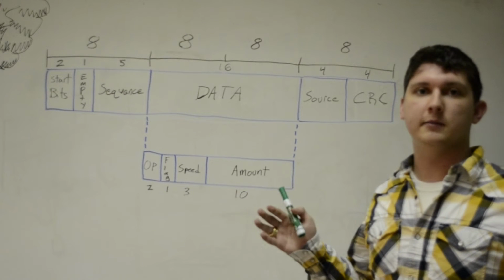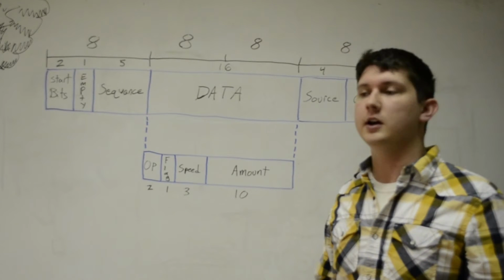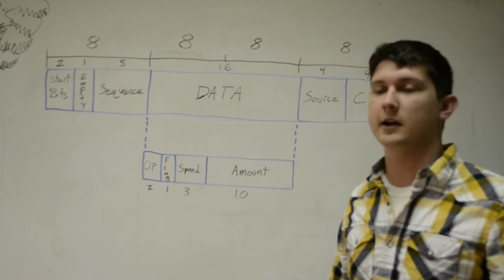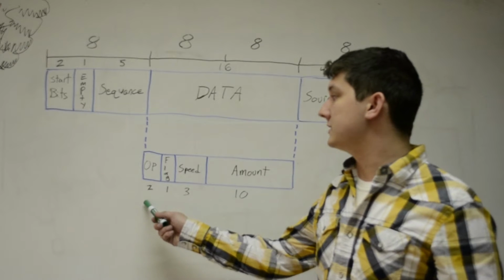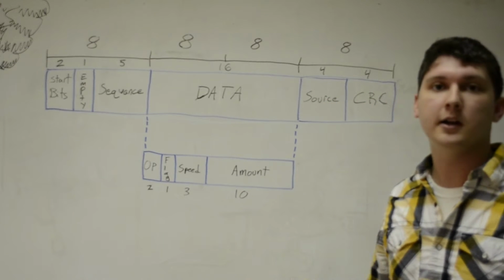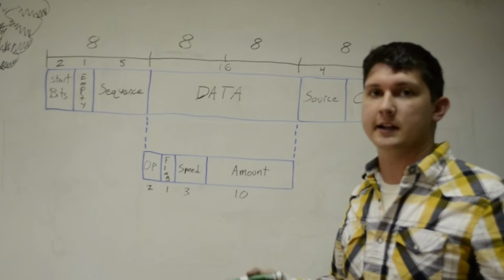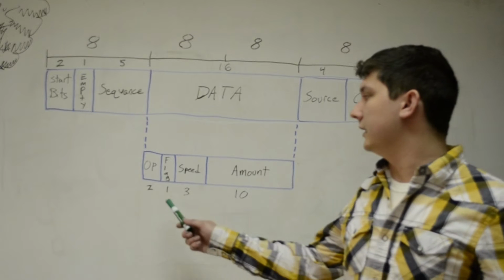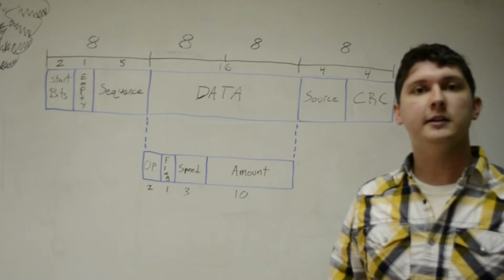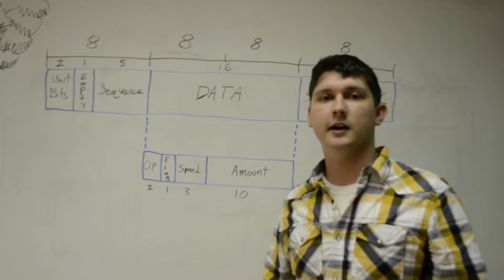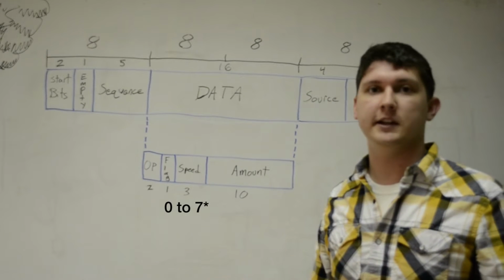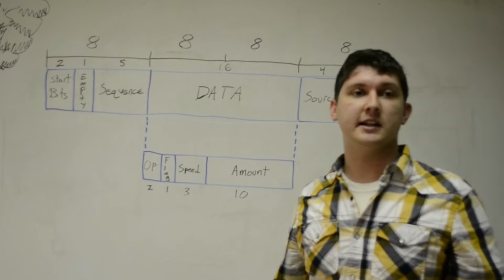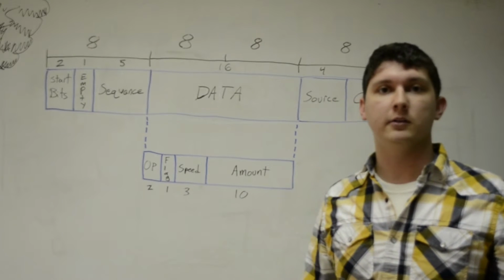And if it's a message going back to the rover, it consists of a few different fields. So if we're going to send a motor command to the rover from the algorithms, we instead put in 2 bits of an operator, which defines whether it should move forward, in reverse, or rotate clockwise or counterclockwise. It'll have a flag. It will have a speed that is 3 bits. The speed will be just 0 to 15, how fast the rover should move or rotate. And it'll have an amount, which is a distance that the rover should drive or a degree angle that it should turn.